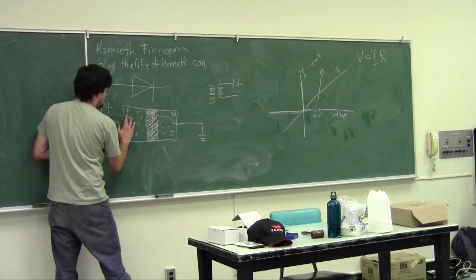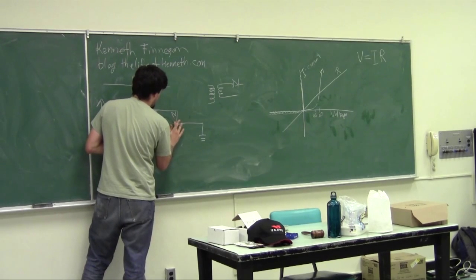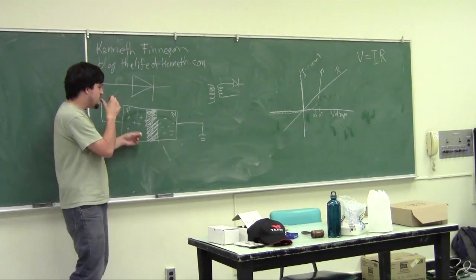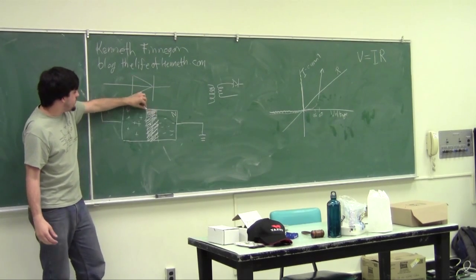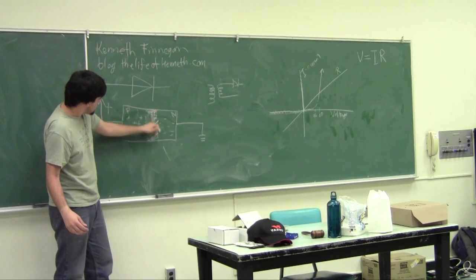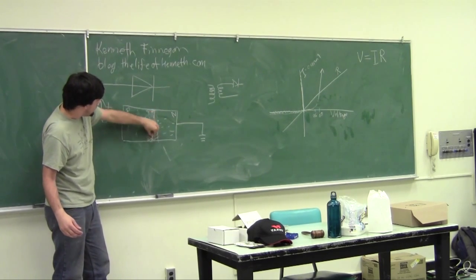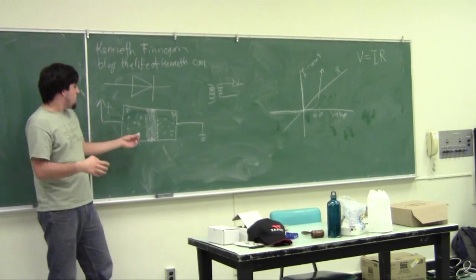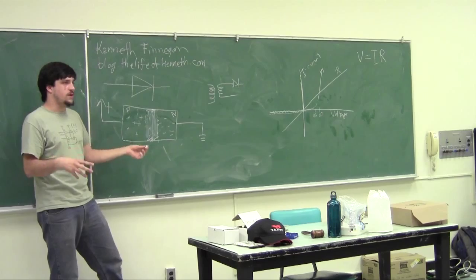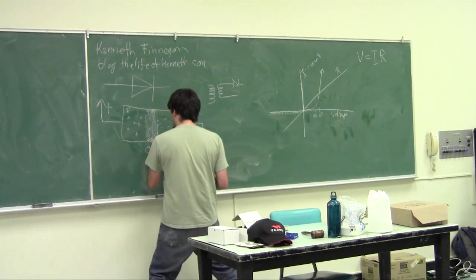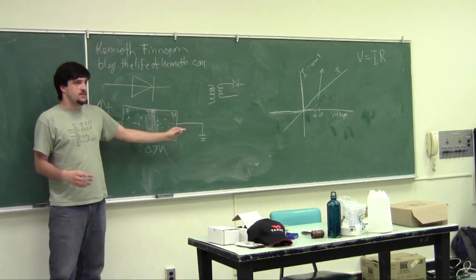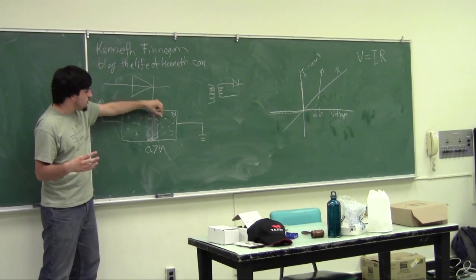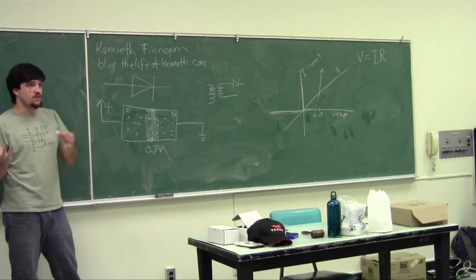All right? But we don't want leakage current, because leakage currents are really small and not very useful. So we want this diode to actually conduct as a full conductor. To do that, we need to apply enough force to this center depletion region to shrink it to the point where it finally meets itself. The P and the N sections finally meet each other, and the depletion region completely disappears. This is why the diode junction has a 0.7 volt voltage drop across it. The force, this recombining force that creates the depletion region, has an equivalent voltage of 0.7 volts, kind of.